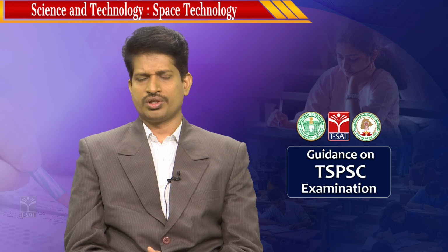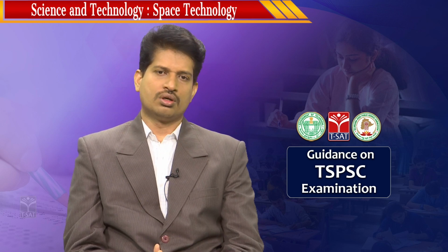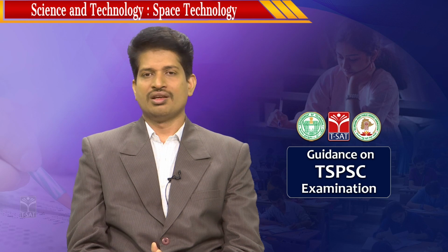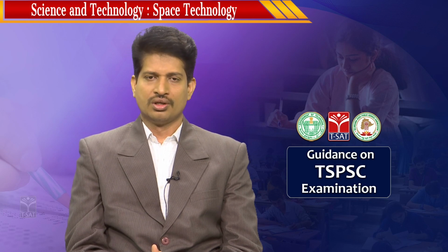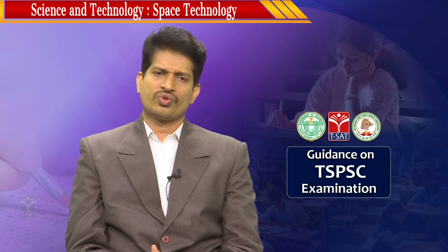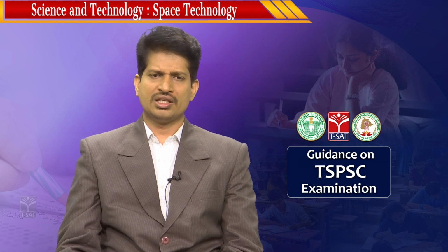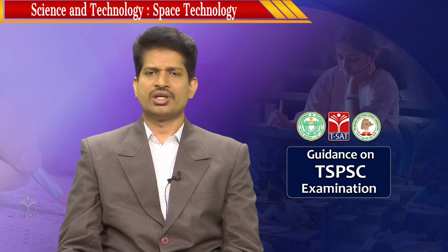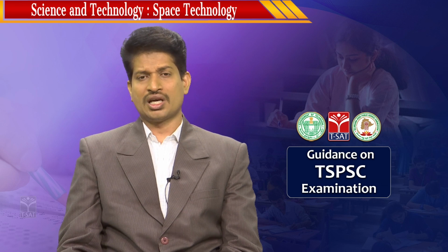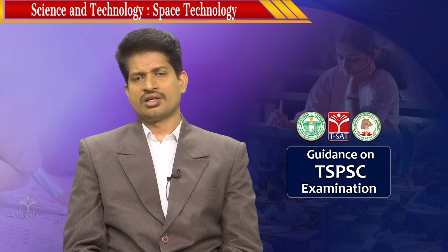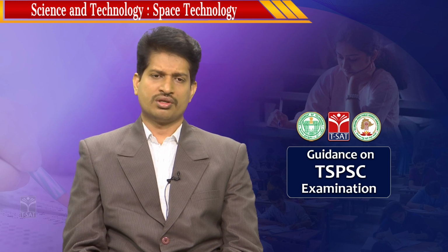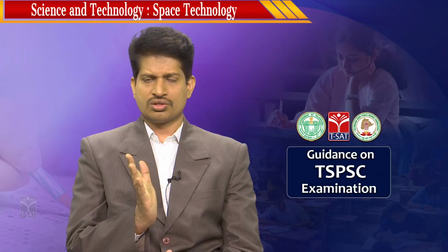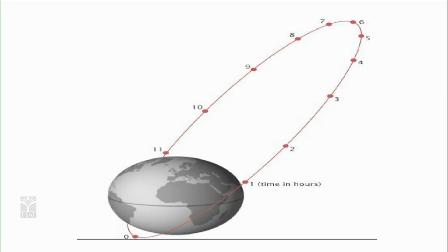The third variant of orbit is the low inclined orbit, or highly elliptical orbit, or Molniya orbit. These are synonymous words. It is described as a highly elliptical orbit because of its real-time orbital shape. It is neither polar synchronous nor geosynchronous. It revolves around the Earth at an inclination of 63 degrees, and the revolution time of this orbit is 12 hours.